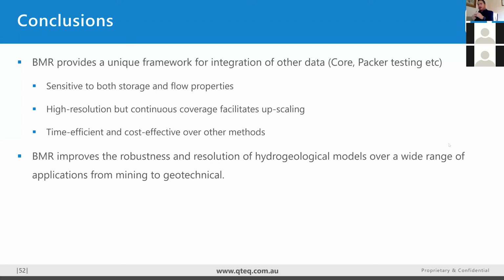So a packer test, depending on the setup, also known as a drill stem test, basically they lower a device down the well, they will set a couple of plugs or packers, and they will inflate them above and below a particular zone, and then they will either inject or extract water over a particular length of time, and they will watch how the formation responds. So if it's a very low permeability zone, they might have to pump for a very, very long time to get a response out of the formation.